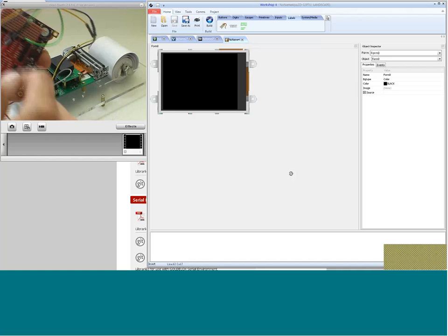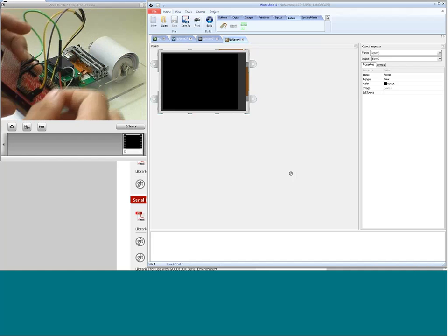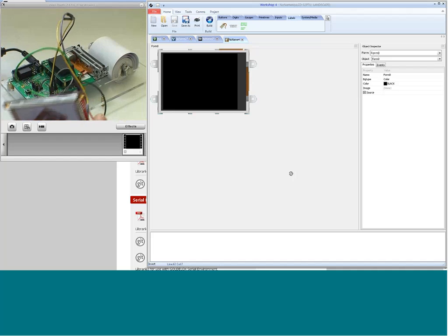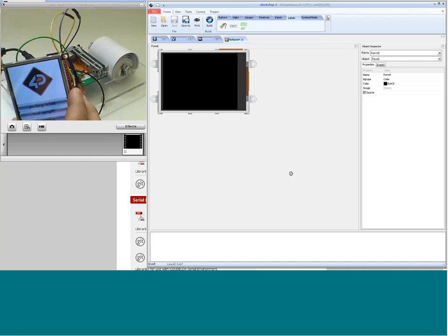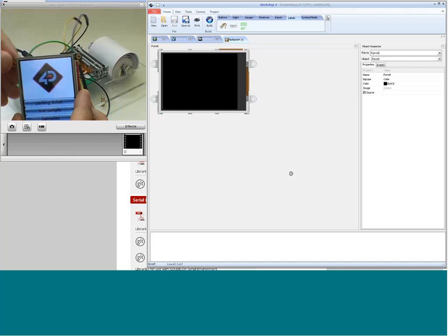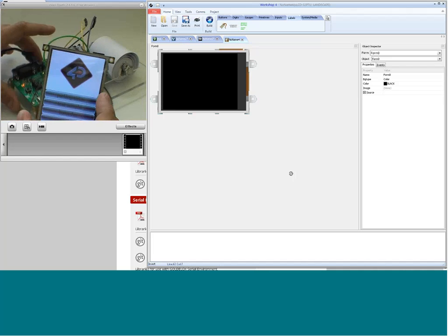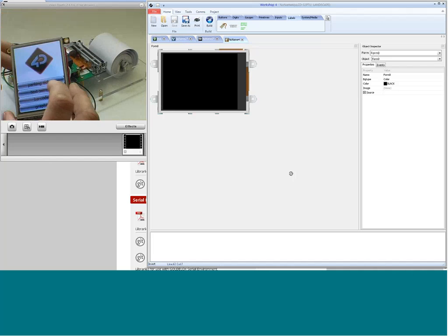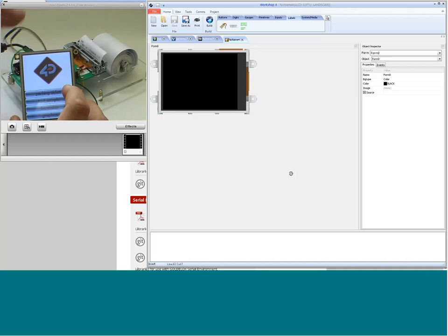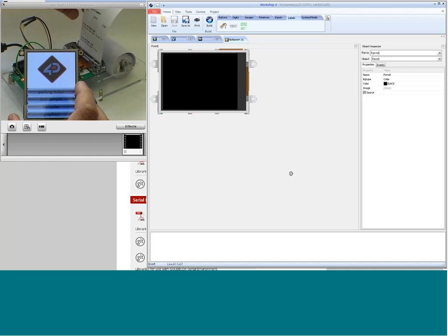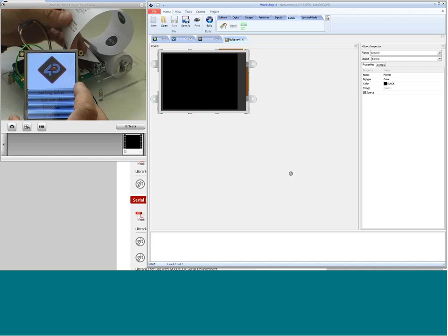So I have the I/O here in the back of the display, and all I'm using is power and serial commands. And so here I have an SD card inserted. It's reading a text file and modifying the file, and accordingly can print now via serial commands to the thermal printer, without any other host controller. So you can do ready applications just with the display.